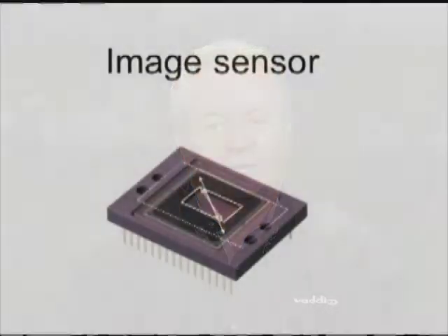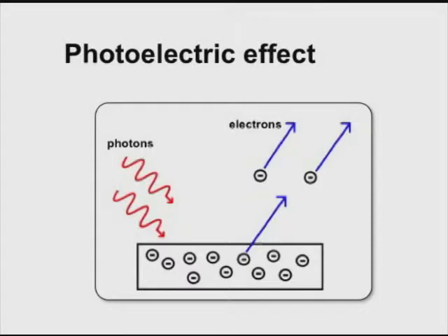However, if your light is a gas discharge light, you will face a situation where your white balance will change constantly. In order to understand this, let's talk about the image sensor. In this case, we'll talk about the CCD. So the photoelectric effect, what it does, the photons reach the semiconductor and electrons are moved out of that semiconductor when the light hits that device.